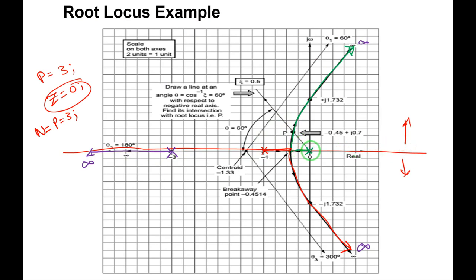The root locus exists in the section from 0 to -1. Yes, from 0 to -1 there is root locus. From -1 to -3 there is no root locus; it is not a part of the root locus. You can observe that from -3 to -infinity, through -3, -4, till -infinity, the root locus is there. But in the section -1 to -3, root locus is not there.